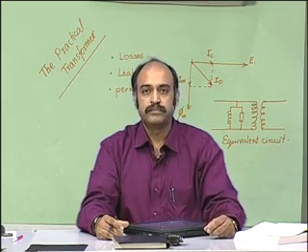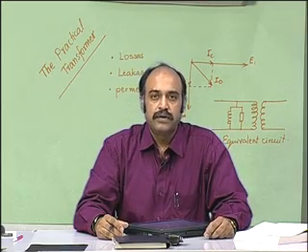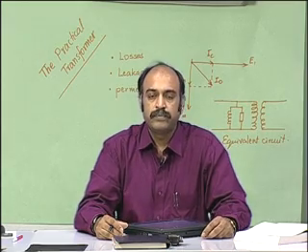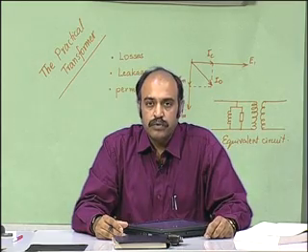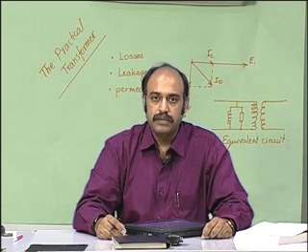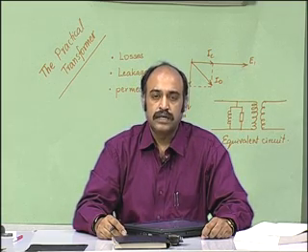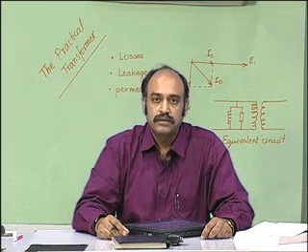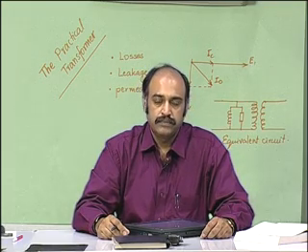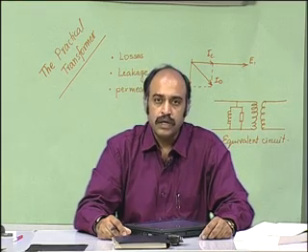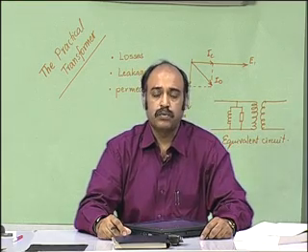Hello everybody. In the last session we were discussing the power transformer. We saw that the power transformer could be used for many applications, one of them being isolation, the other is for step up or step down, and the third one is for impedance matching. In the case of isolation transformers, the turns ratio is normally kept at 1:1,